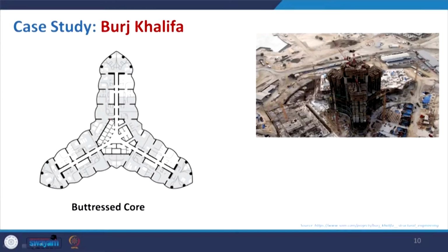Now, this is a detailed view. What I was talking about, these shear walls and this core are facilitating a better view for all the hotels and all the residential areas, which makes them very attractive. So, this Y-shaped structure is called a buttressed core. This is an under-construction building, where you can see that the core is being made here, and the wings are actually under construction.